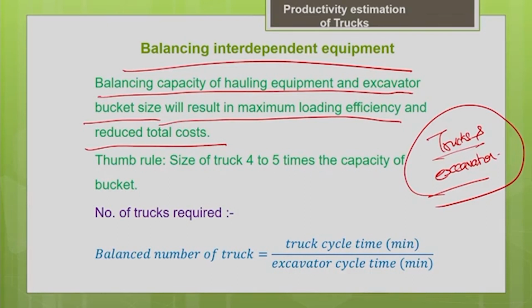Based upon the studies, they have found that the truck capacity should be 4 to 5 times the bucket capacity.